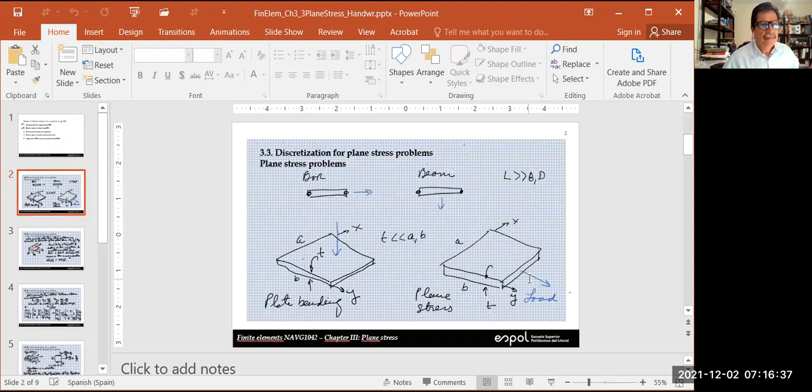So in this case, as we said in this slide last Monday, this plate supports forces only in the same plane of the plate, okay? So this is what we call plane stress. On the contrary, when we use plate bending, this is something that we studied in ship structures, but we don't have the time, we are not going to work with plate bending in this class in finite elements, okay? But it's a good idea that you can recognize the difference. When we have linear problems and you have both, you can solve one, solve the other, and you simply superimpose results, okay?